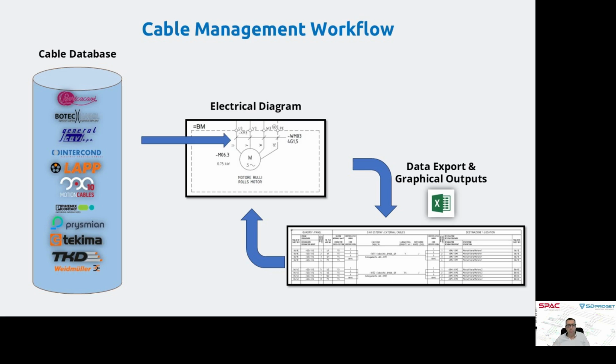Eventually, by pressing simple buttons, so simple automatic operations, I generate outputs that I know we've put on this slide. For example, you see the output where there is mountain on the left, valley on the right? In the middle is the indication of the name of the cable with its length, with its description, and we have each vane to which terminal, to which wire it connects, both on the left side and on the right side. This way, the cabler can safely wire the cable. All this information can also be generated in Excel so that the wiring engineer can wire by reading an Excel file.